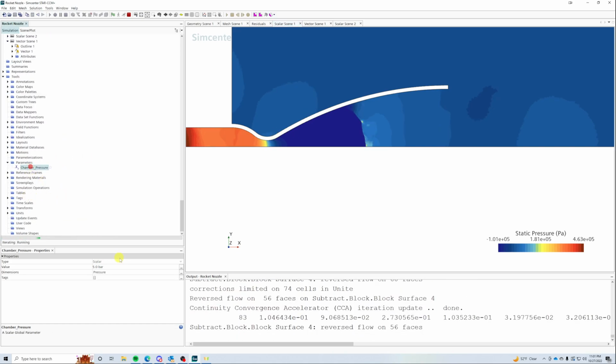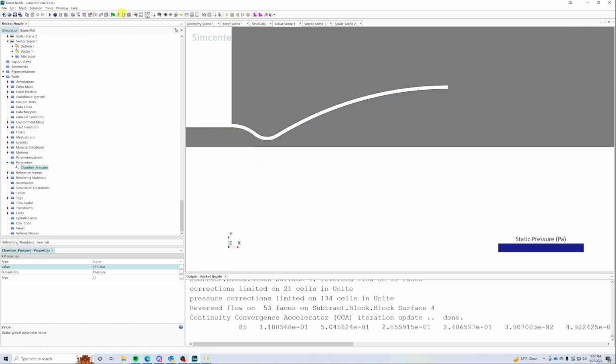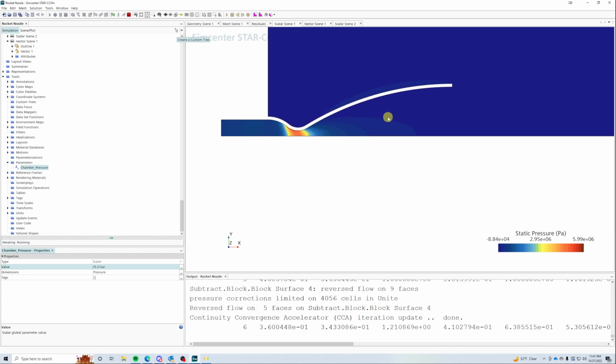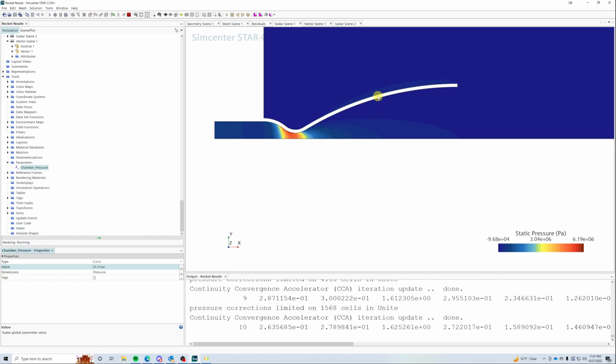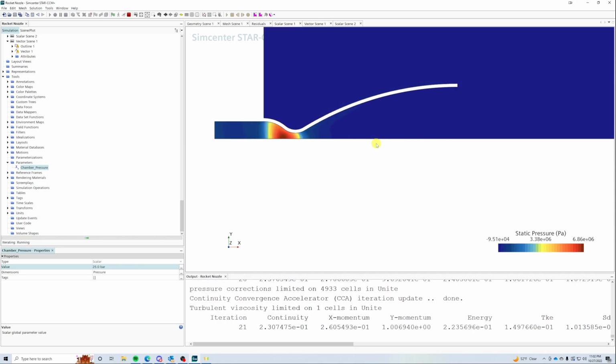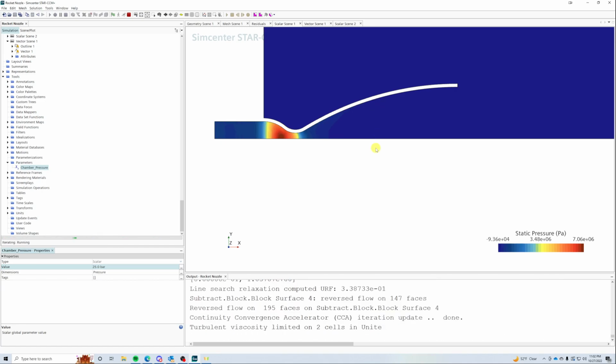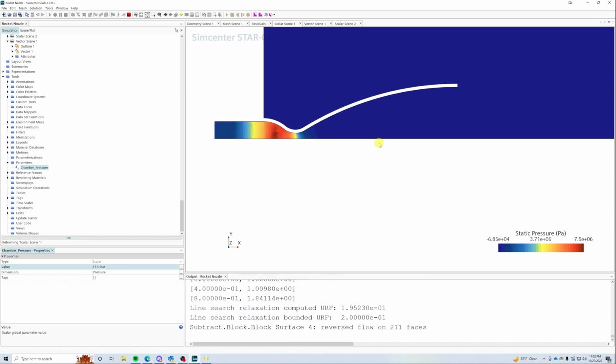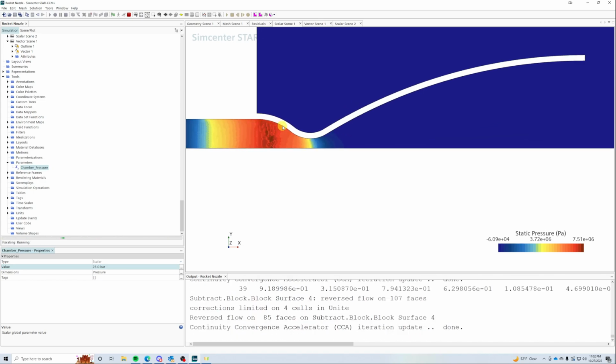Okay, that's what's going on. So what was happening is, as it was trying to accelerate, pressure was dropping so far that there was a threshold where it basically got to vacuum pressure. You can't go any lower than a true vacuum. So there was a hard stop there where it stopped accelerating, which caused a normal shock, I believe. Which is why we saw that region of very fast flow and then a region of very slow flow.